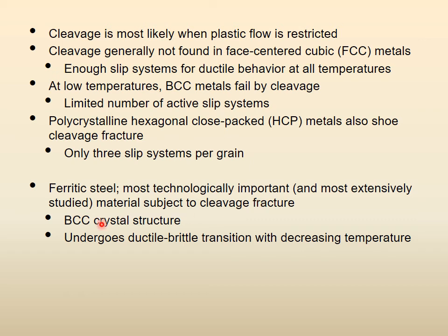Why? First, it has a BCC crystal structure, and we know that BCC crystal structure has a limited number of slip planes. Therefore, there is a restriction on plastic deformation. So it is already a system where cleavage will be possible.